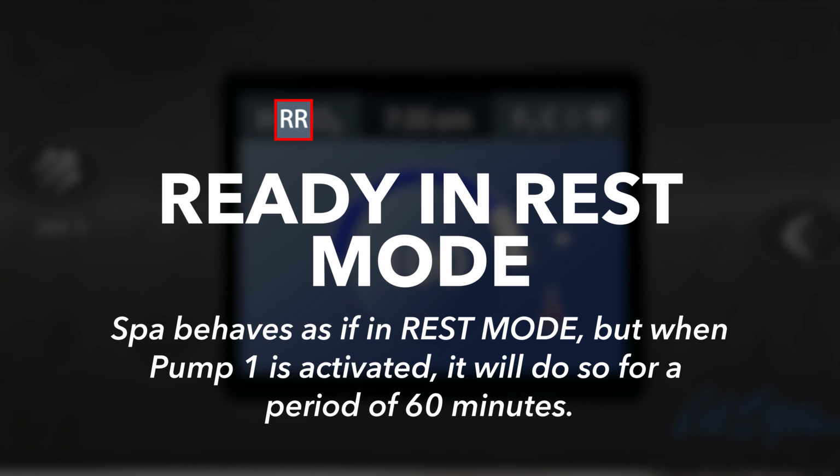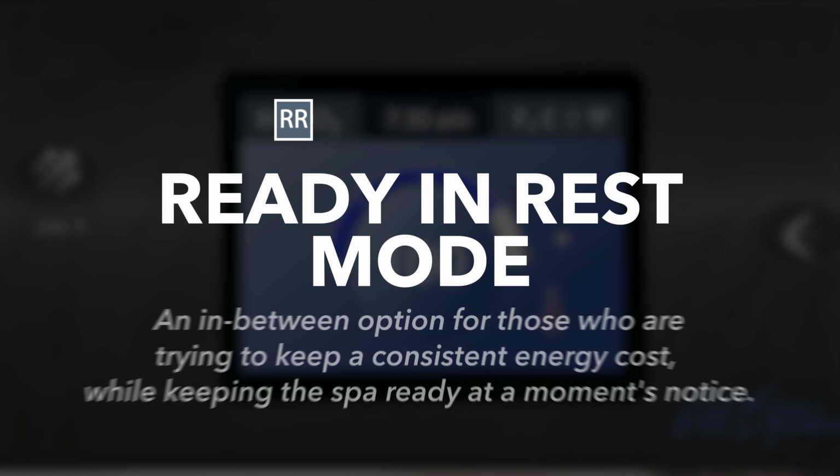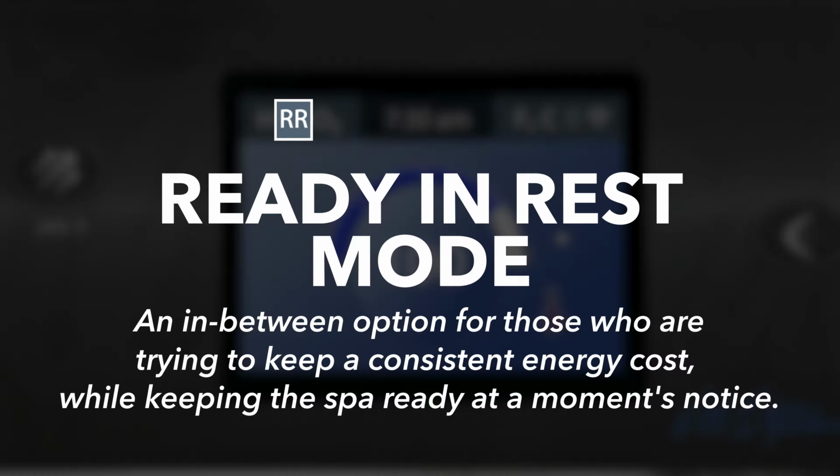Ready in Rest mode. This unique mode is the intelligent approach. The spa mainly behaves as if it was in rest mode, but when you press the Pump 1 button, the heater will automatically activate for a period of 60 minutes. This is an in-between option for those who are trying to keep a consistent energy cost while keeping the spa ready at a moment's notice.